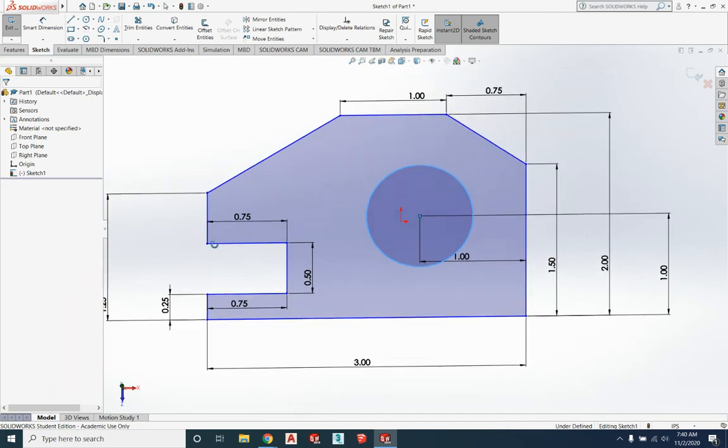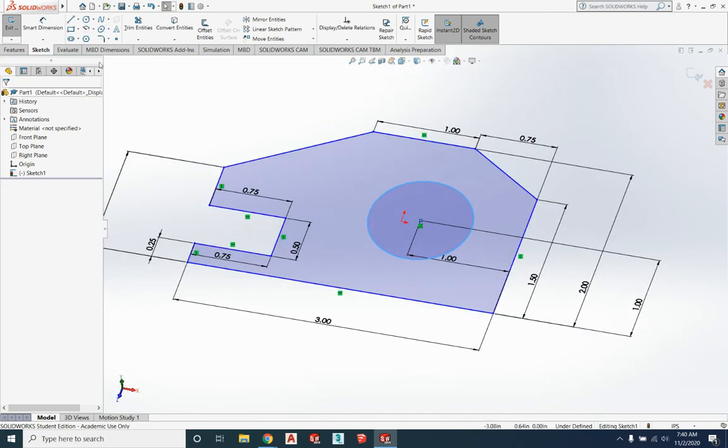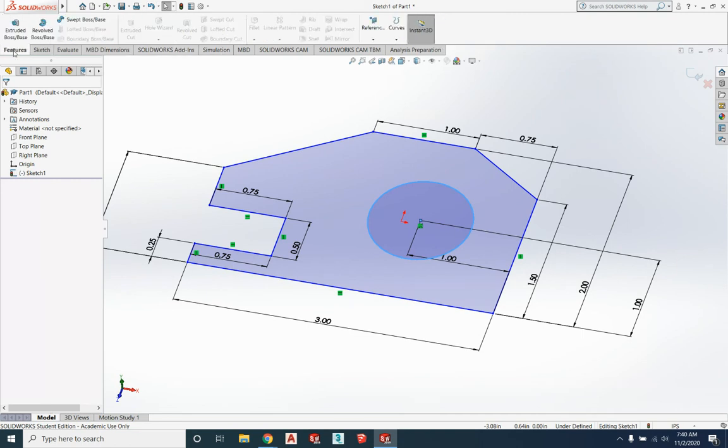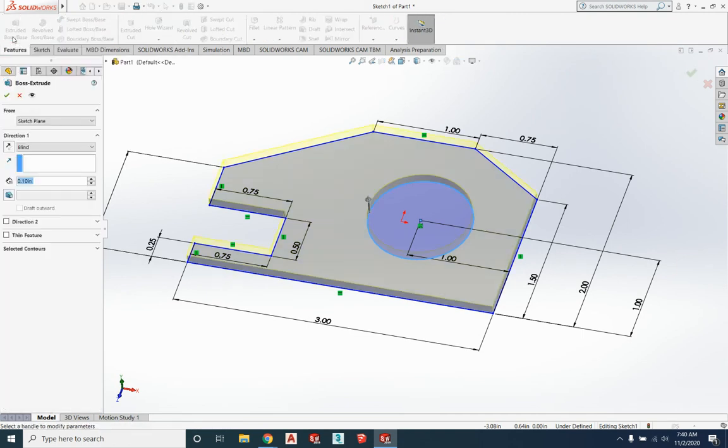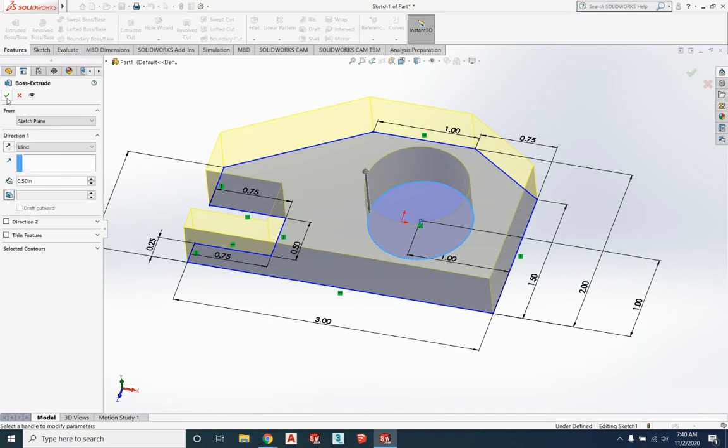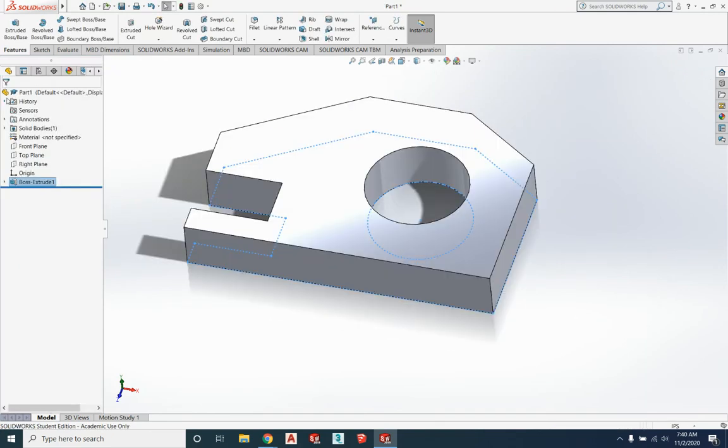Again, from the sheet, it was a 1/2-inch thick, so we know we've drawn it and it's dimensioned properly. So now the feature is we're going to extrude it. That's 0.1. Let's change that to 0.5. And there we go, we have drawn the incline support.